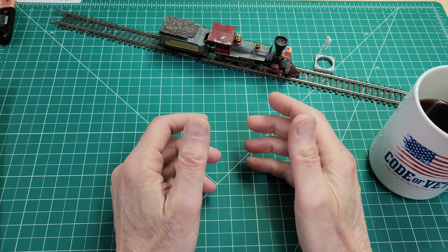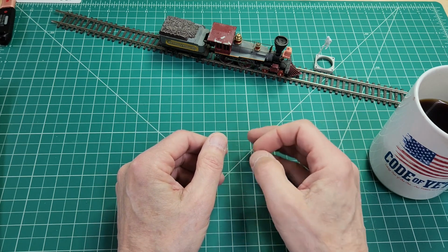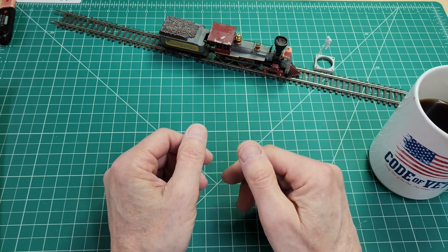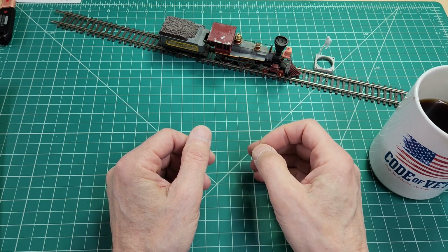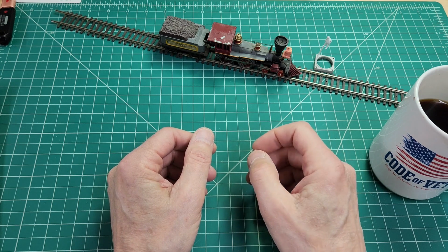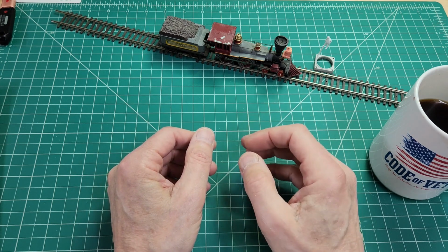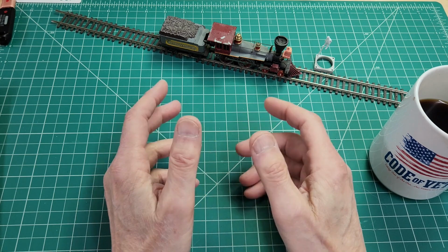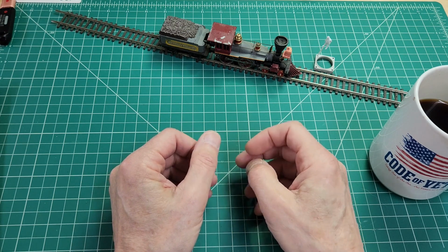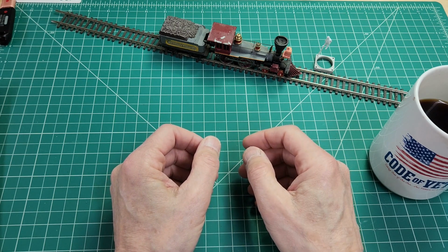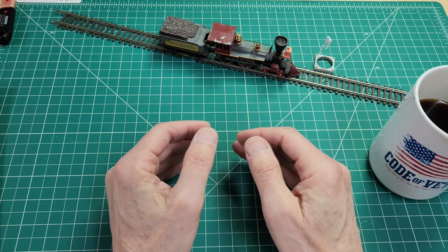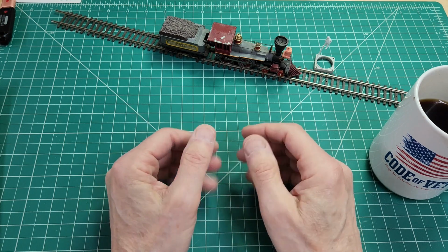This invites a side discussion about the host shield library's architecture. The library treats its USB function as a hub. Emulating a hub means that more than one USB device may be connected at a time. To accommodate multiple devices, the library implements an array named devconfig. I know, it's the configurations of the devices attached, I guess, is what they were thinking. Each entry in this array, which is indexed by a driver number, has the value of a pointer to an object of a driver class.